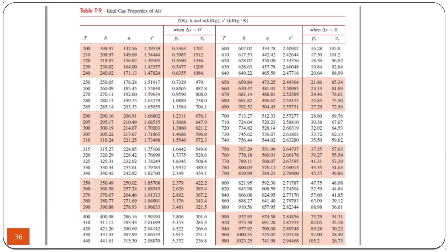So the enthalpy change is found from the enthalpy at 290 minus 199.97. So the enthalpy change during the temperature change from 200 to 290 is the enthalpy change given here. You can also find the internal energy change from, let's say, 200 to 206.